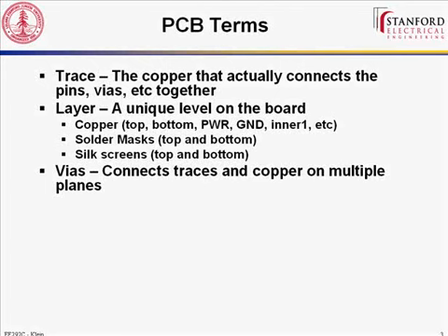For the designs that we're doing in this class, and for most of the designs that you all will do, at least to start with in the real world, the vias will go all the way through your board. So once you drop a via, you can access it on any layer of the board. That's important because it makes the assembly process much easier for the PC board fab company, because they can stack all the boards together, laminate them, and then plate the vias all at once.